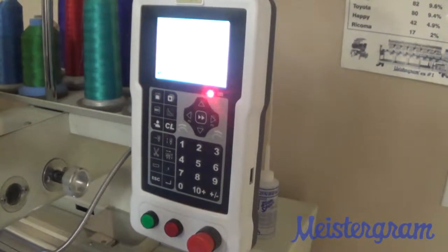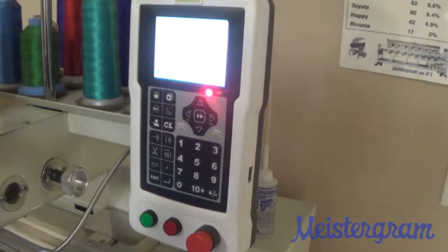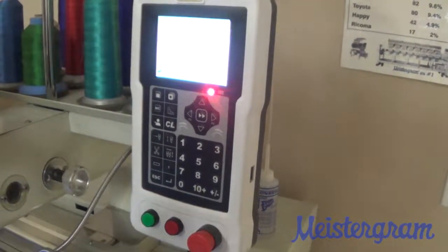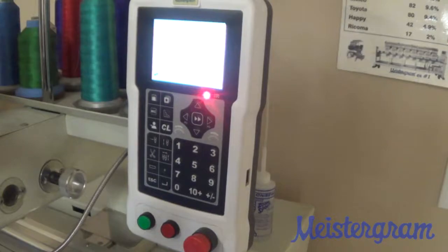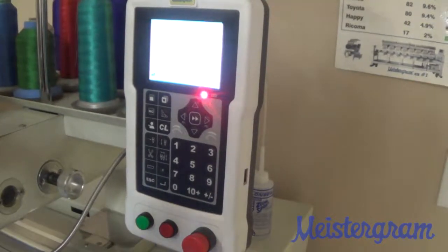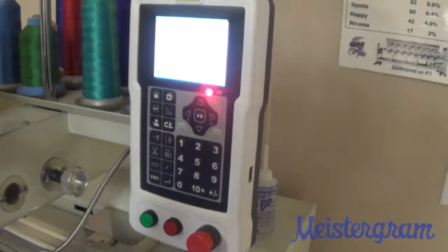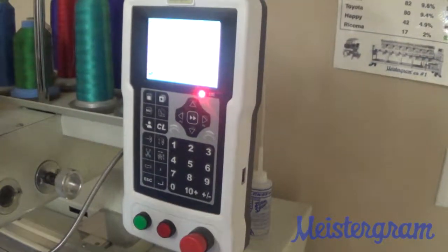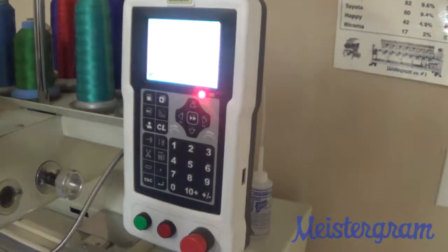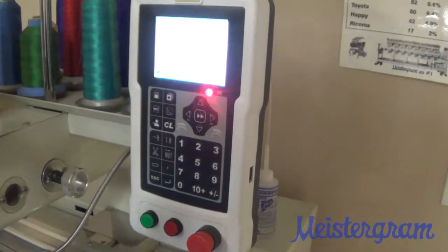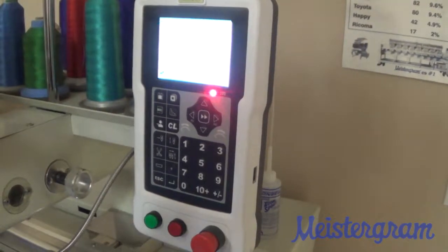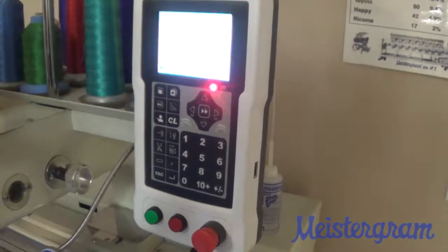Acceptable voltages, if you can measure using a multimeter, or you have someone that has a multimeter, are 2.85 volts all the way up to 3.1 using a DC setting on the multimeter. Anything under 2.85 will cause a problem. If the battery is not the issue, make sure you check the wiring in that area where the main board is located. Make sure everything's plugged in.